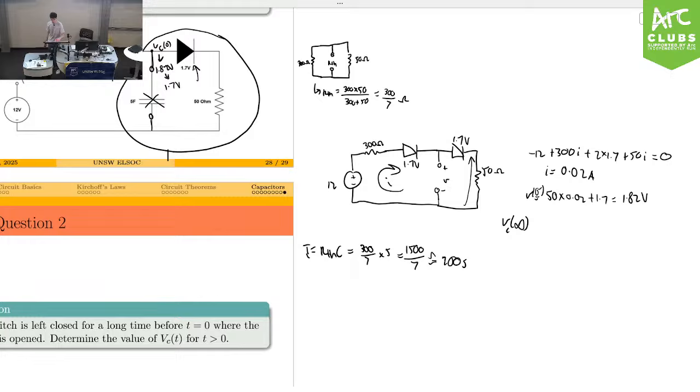So ideally, it'll stay at 1.7 volts. Because what is a capacitor essentially? It's just a store of charge, isn't it? It's like a temporary source. So you charge it up, and then it discharges to 1.7, and then the diode reverses, and the technical word is that it clamps the voltage at 1.7.